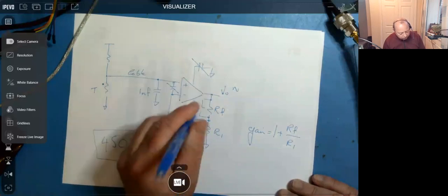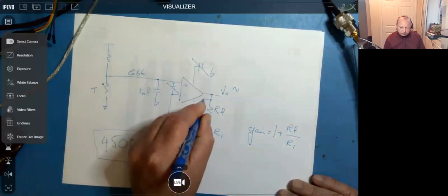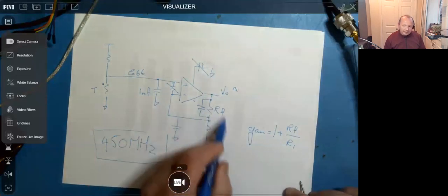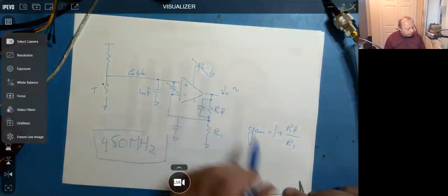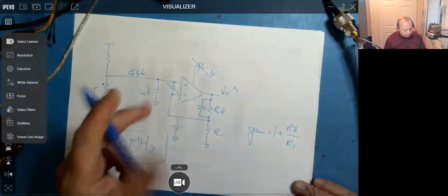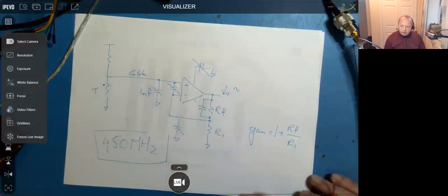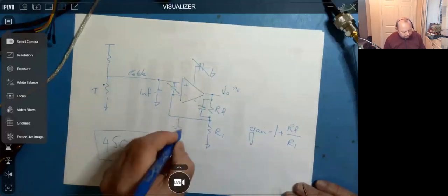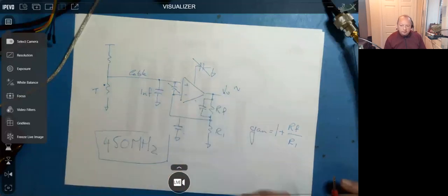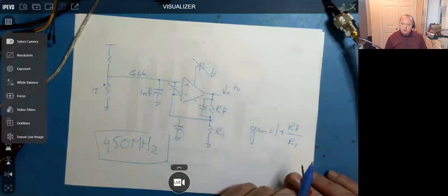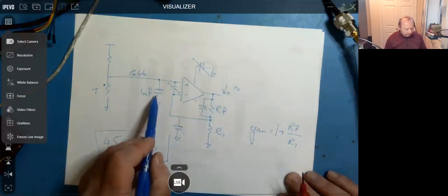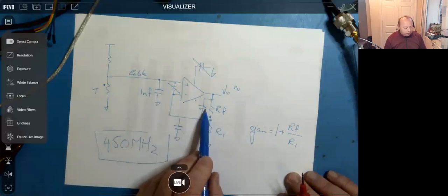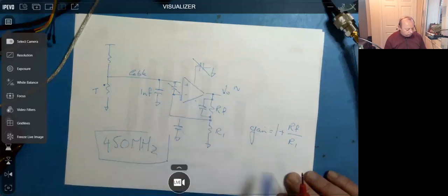And we have spoken about active amplifiers before, active filters. So this is actually then operating as an active filter, and it took out some noise. But as soon as I started to remove this one or this one, things started to go back to their old ways again. So then I put them back, and the problem had disappeared. So my solution was 1 nanofarad here, and across this feedback here. All the other ones I then managed to take off, just those two actually, and I got away with it remaining stable.